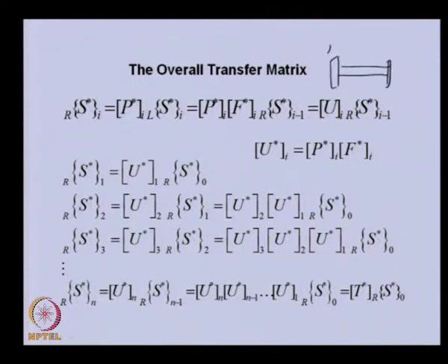if this is I minus 1 disk, this is ith disk. So, the state vector here, which is right of I minus 1 disk, and the state vector which is right of ith disk we are directly getting. So, information from here we are directly getting to the right of ith disk.